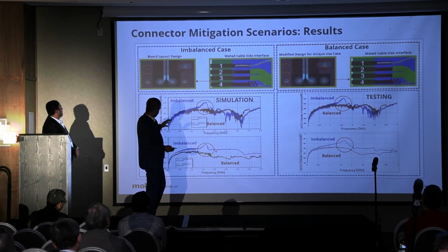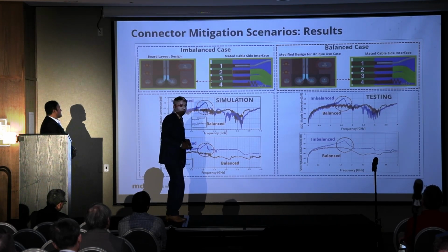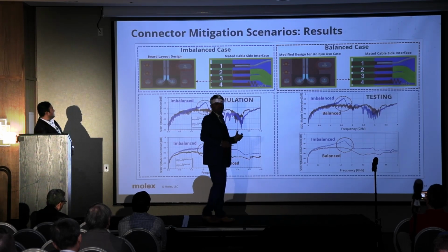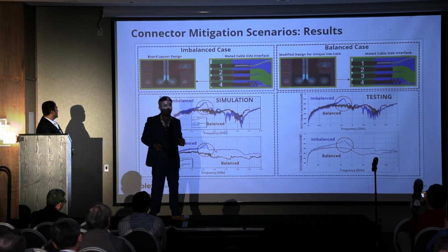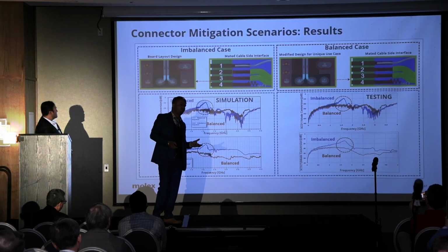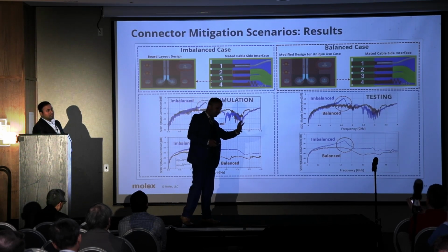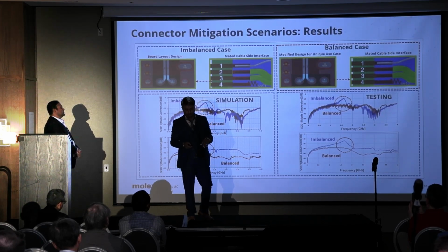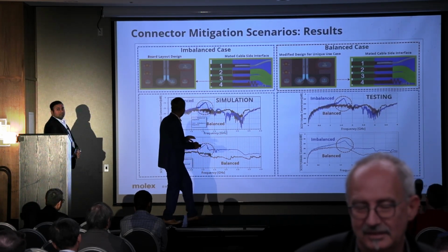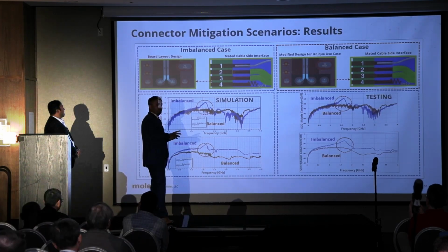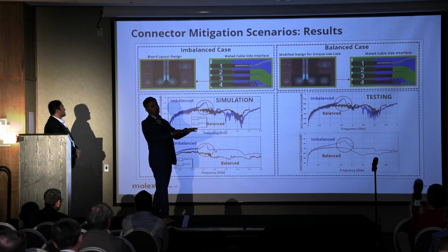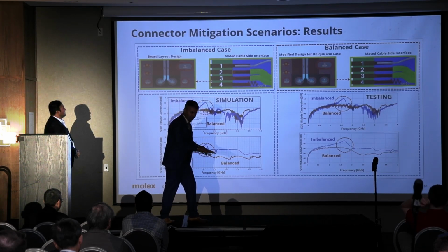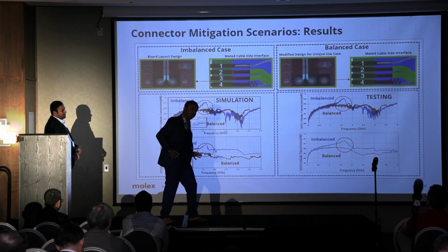Yeah, so we created a board and we did testing also. So as I said, in a unique application, for example a single channel Ethernet or any other application where we have only one cable, and inside that cable bundle, let's say I have one pin as a drain and the other two pins as a differential pair. So in that kind of application, what will I do with pin 4? Because pin 4 is a part of the return path up to the PCB, right? It's giving very good common mode performance on a board level. Very good design. It's like a coplanar transmission.